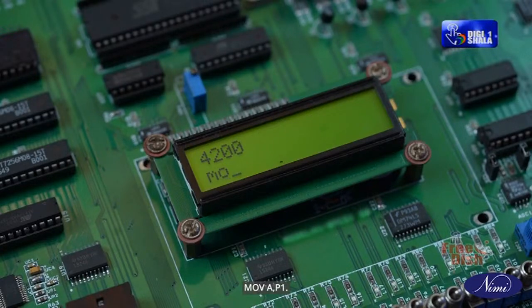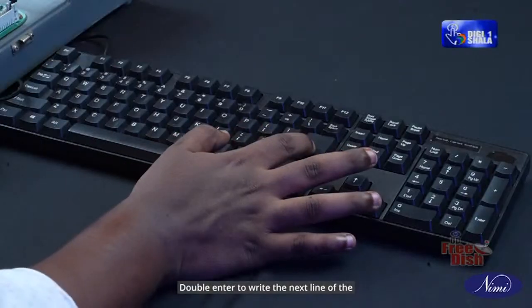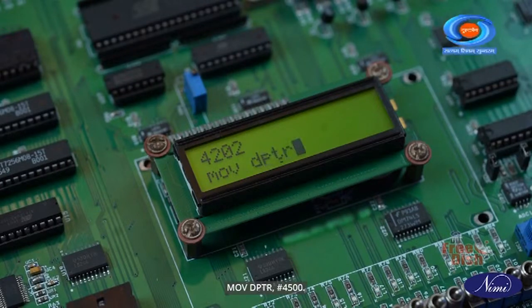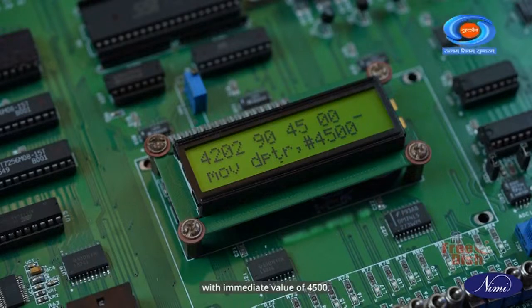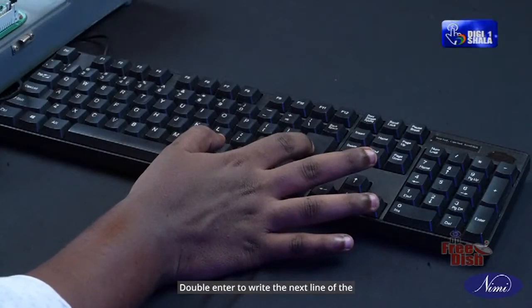Now enter MOV A, P1. This means moving the port 1 value in the accumulator A. Double enter to write the next line of the code. Now enter MOV DPTR, #4500. We are assigning the data pointer register with immediate value of 4500. In this address, the output will be stored. Double enter to write the next line of the code.